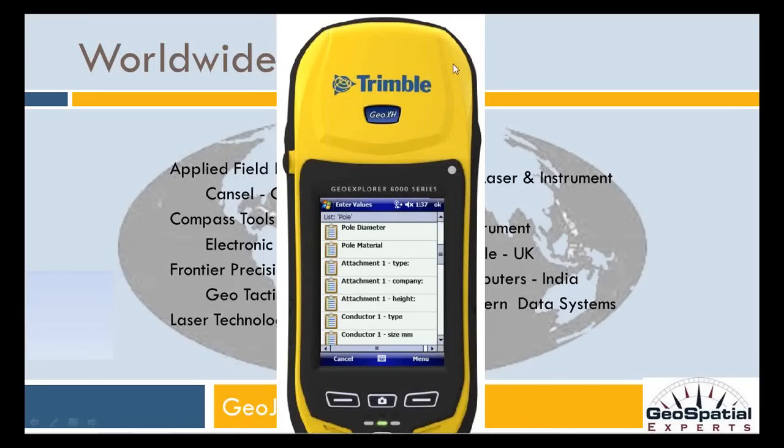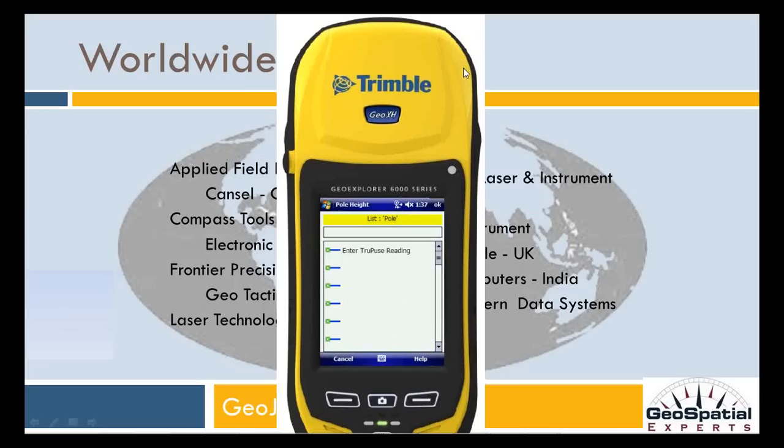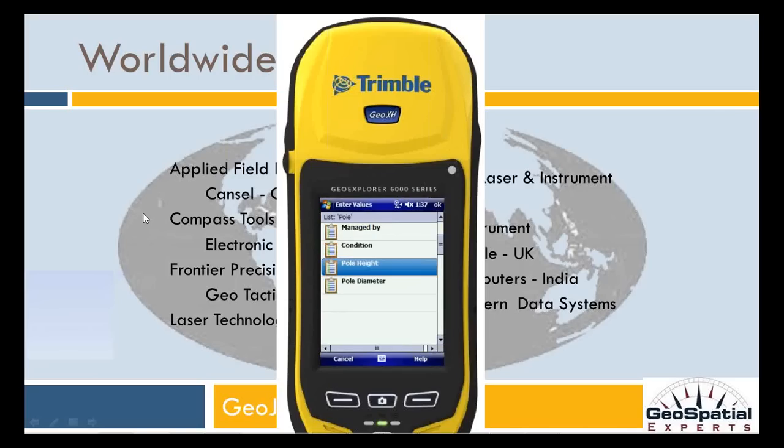Now, say I wanted to shoot the height of that pole. It's going to bring you to the screen where you say enter the true pulse reading. From the true pulse laser, I'm going to shoot the distance, and then I'm going to shoot the top of the pole. And then I'm going to shoot the bottom of the pole. And then it's going to give me a reading of the height. Now, obviously I'm shooting indoors, so that's not accurate to the picture of the pole, but it works the same way out in the field. It takes distance and the two angle measurements, and then will give you the height overall. So I say OK, and that height that it collected is populated directly into the field within GeoJot, and I'm ready to move on to collecting my next piece of information.